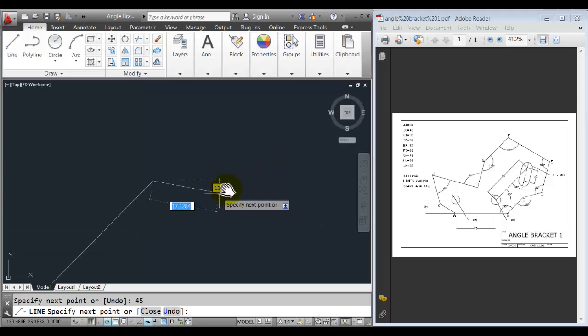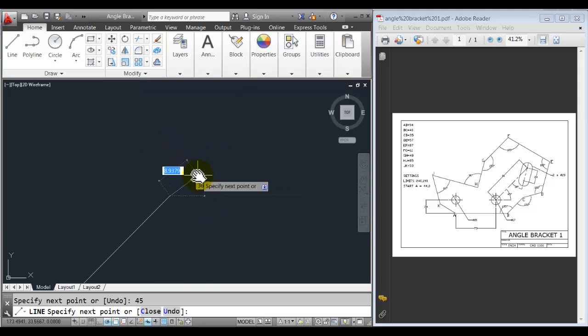For the next one, we're going to take a look at this because when we picked relative to last segment, we actually were able to say that this straight line is 0. You can kind of see that where it says relative polar. It kind of shows us that 0. But it still keeps us at a 0 here in this direction. So we need to calculate now 150 from the line we just drew to this new line.